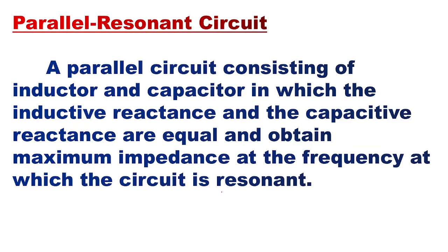The other way to look at the parallel resonance concept is that a parallel circuit consisting of inductor and capacitor, in which the inductive reactance and capacitive reactance are equal, obtains maximum impedance at the frequency at which the circuit is resonant. Now what does this mean?